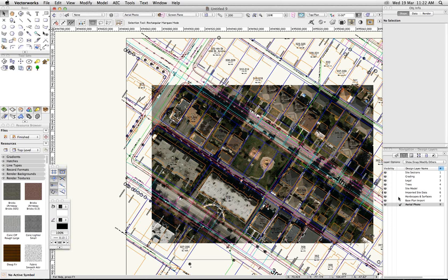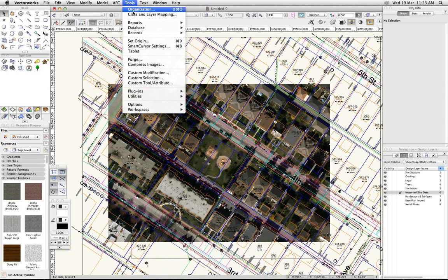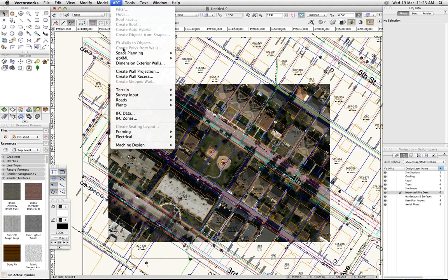But I would say, just like I've seen a much greater amount of geo-referenced information in the past few years, and that's becoming a bigger and bigger thing. In terms of getting the elevations into your site model, the best way to do it is this import survey file command, whereby you will just get a text file from the surveyor instead of having all of the contours by DWG. There are many ways to start your site model in Vectorworks.